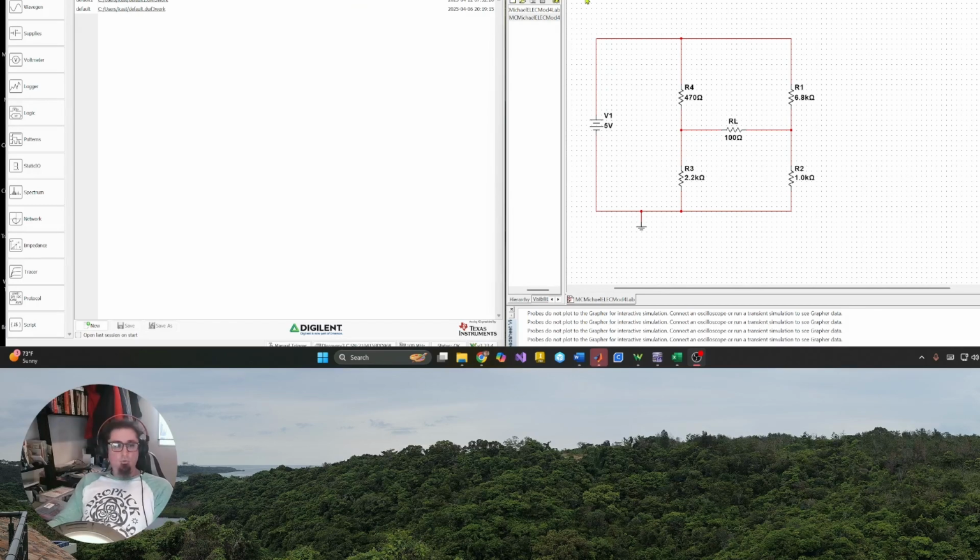So first off, we're going to look at the circuit we've built up. We have V1 right here, and then what we have here is a complex circuit. But as soon as you start analyzing this, especially when we're using the Thevenin equivalent, this right here becomes removed, and you can start looking at this circuit as more like a bridge circuit, where these would be your loads here and here.